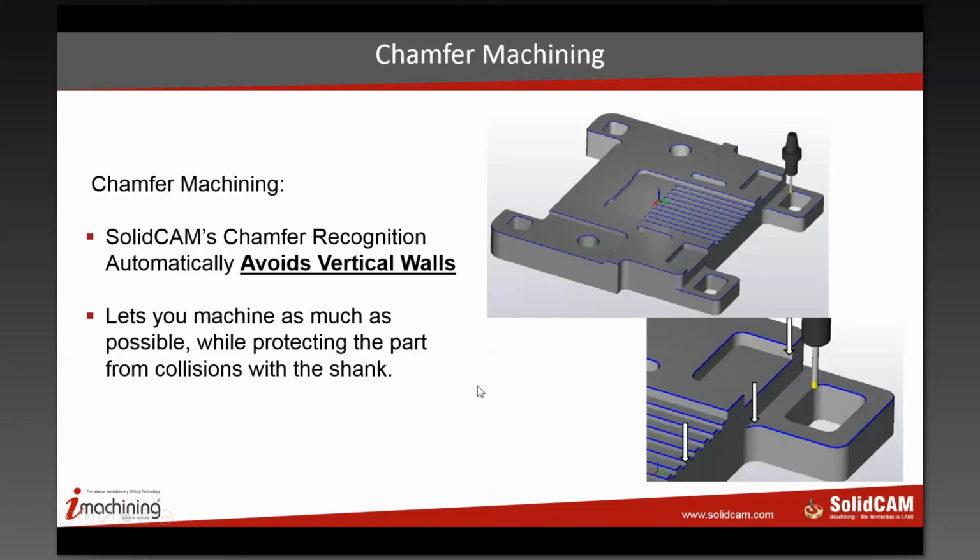Well, the safety offset is very simple. If you notice that little picture that we have in the bottom right-hand corner, you'll notice that the tool path is actually coming up towards the wall. What the safety offset actually does is prevent the tool from coming up to the wall itself, thereby protecting it from any gouge from the tool into the wall. So you can get as close as you want to the wall without worrying about damaging the wall. It's sort of a safety factor where you can define your entire geometry and don't have to do an edit geometry to get close to that area. It really, really works phenomenally well. One of the best features in there.